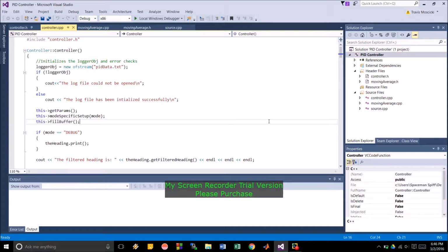Now let's say that we have a unit step function input. We're just going to drive this at 1, just some value. A P controller is proportional to the error: if you've got a lot of error, you're going to have a lot of response, and if you've got a small error, a small response.